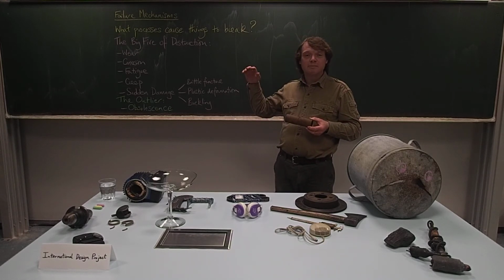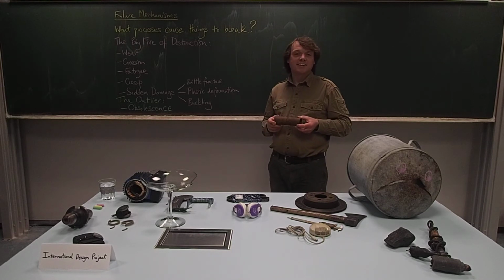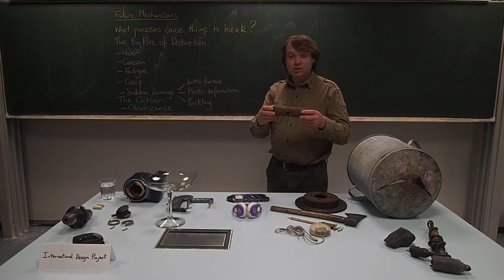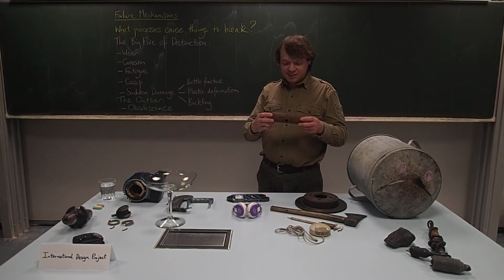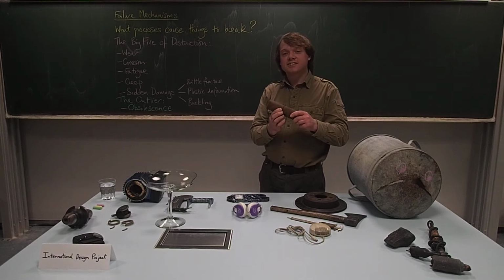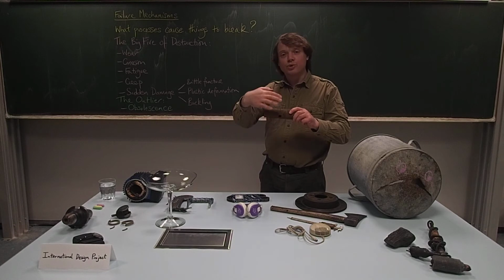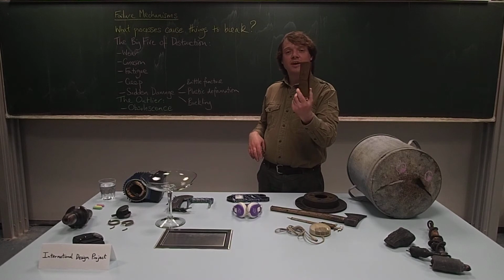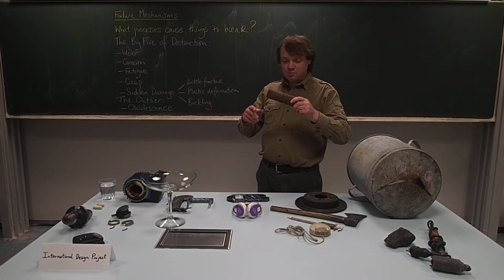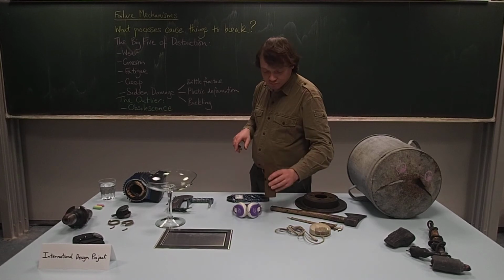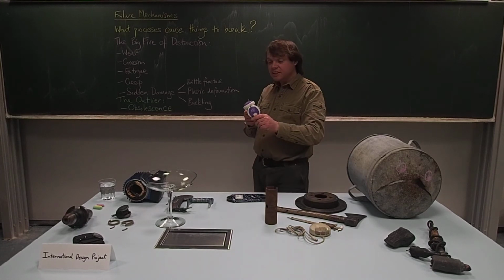But the fatigue limit is usually something that's below the elastic limit for the material, so something you need to be careful of. Here, this is a bush from an excavator, and you can see here that it's presumably been placed in bending somewhat in the center, because there's a slight groove so that the grease can get around it, and over time it's cracked from this greasing hole around the edge there. This would be something that would be under quite a high load in operation, probably something like 11 tons force, if I remember rightly.